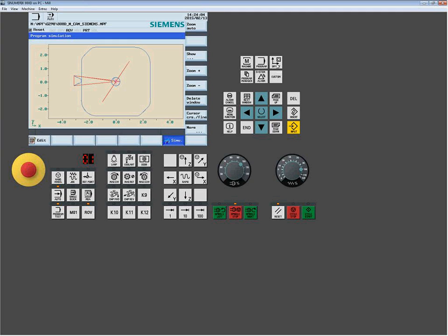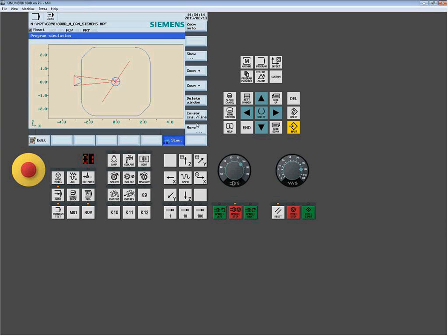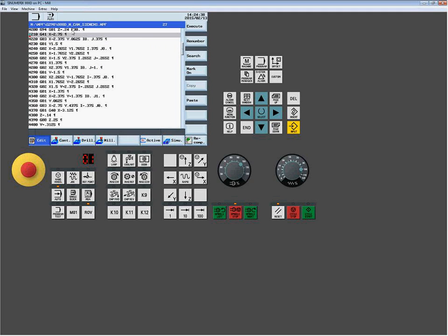One of the things you might do would be say, well, what happened if I went to tool 1 and dramatically changed my radius to maybe a 0? What happened when I simulated it? I would get a different result. When I look at this profile, I'm still going around the exact same path. So how I adjust the radius on this program, it doesn't seem to have any resulting change. What's really happening is if I was to really run this part, it's actually in the offsets for tool 2 because they have set this machine up.